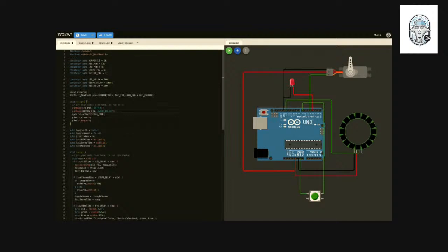What the pull up does is that when there's no activity on the line, it pulls it up to the voltage. That just sort of helps you avoid false positives when somebody presses a button. Otherwise, randomly, there's some delays in how the electronics react. You might get false presses without a pull up.